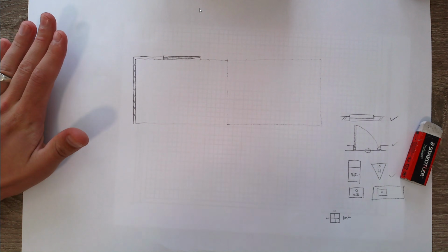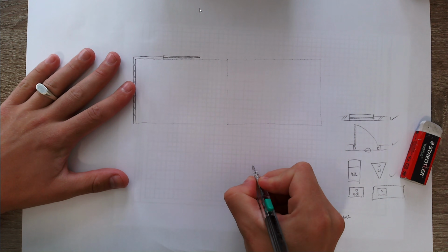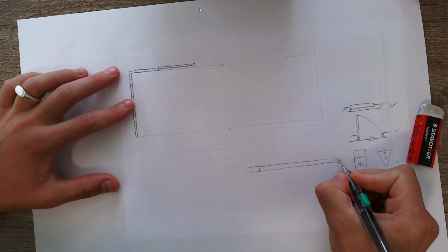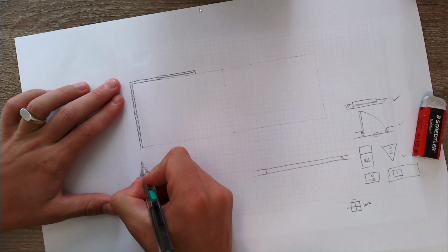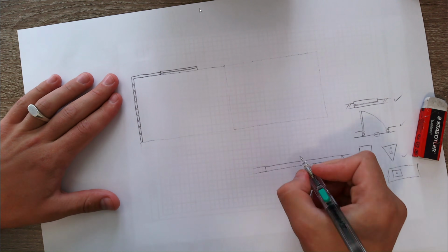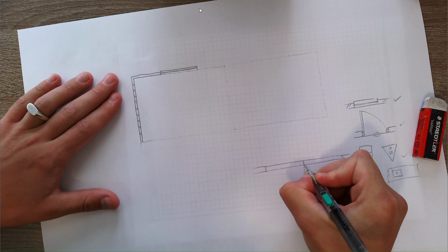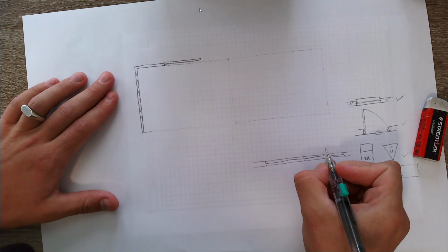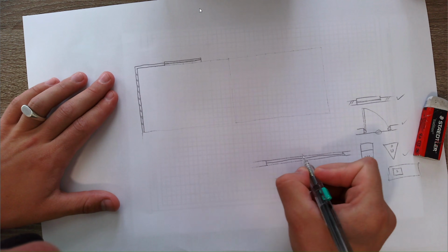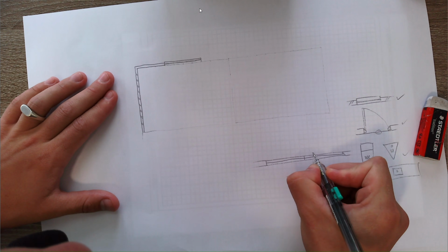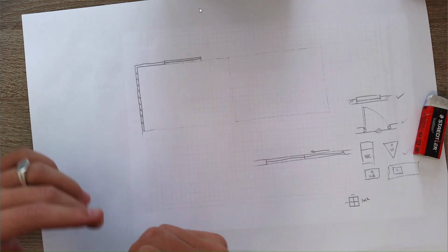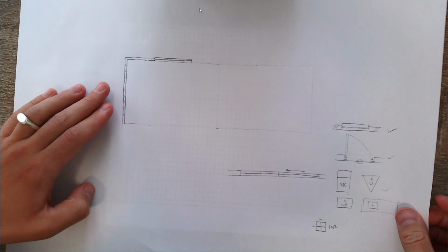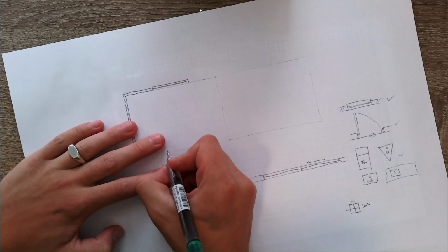Remember that each classroom must also have a sliding door that needs to open on the covered walkway. Now, a sliding door, we're just going to half it and half it, and then we need to give the sliding direction of one of the panels. So you can say that that door opens to that side. So you need to put in a sliding door at each classroom as well. So I'm going to put one quickly here.